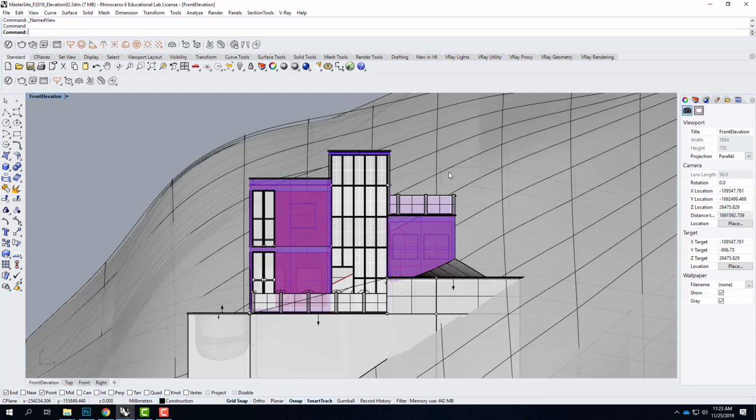And we're going to use a command to do this called make 2D. And I would say that this is probably second to maybe project, one of my favorite commands in Rhino. It's very, very cool to be able to create a line drawing from whatever view that you see. This, by the way, doesn't have to be limited to just a flat parallel projection. You could create a line drawing out of any perspective in the same way. Furthermore, the line drawing that it creates are all live lines. So when we get into Illustrator, we can manipulate the lines, we can work with them, etc.